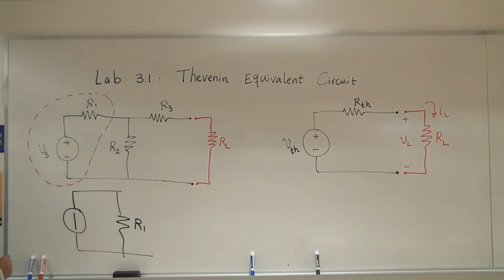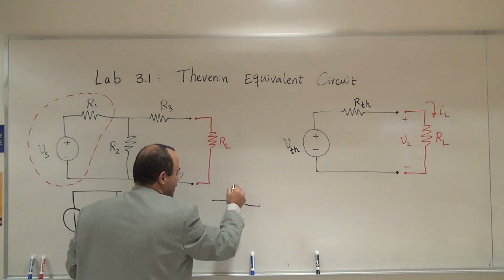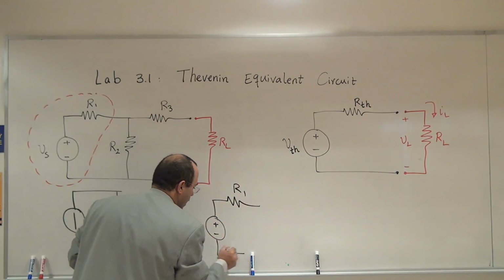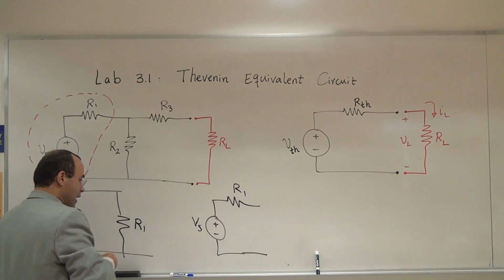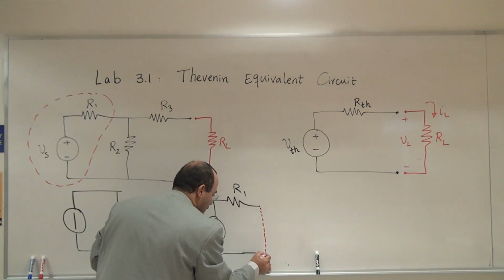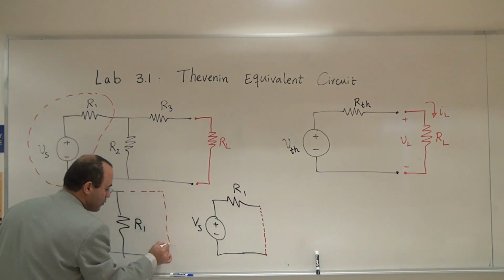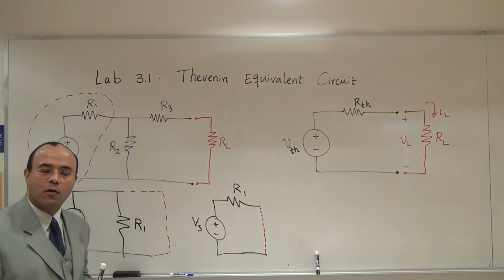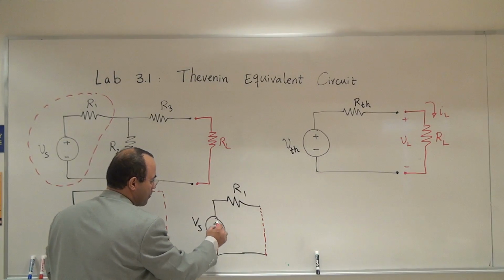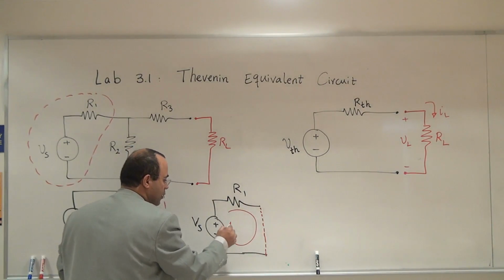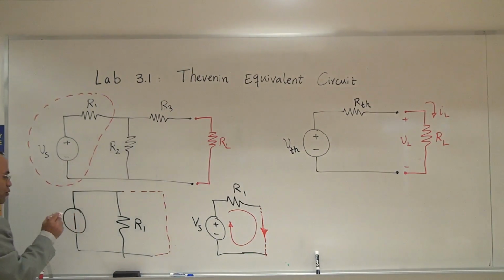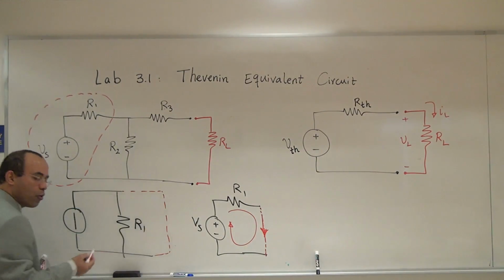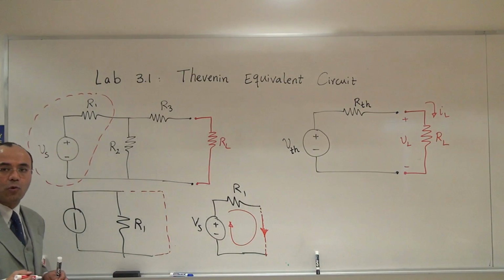It's going to be a current source for sure. And I need to identify the direction. Now, if I take this in my mind, that's going to be R1, and this one is going to be basically Vs. As an isolated element, if in my mind, just momentarily I have this shorted, I need to have this one shorted as well. I want to have the same behavior outside. Now, if you take a look, this is plus, this is minus, and you have R1 in the loop, obviously the current is going to go like this. Therefore, the current in the short line is going to be like this. I need to make sure I assign a current direction so that when I have a short, I would have the same direction on that short line.